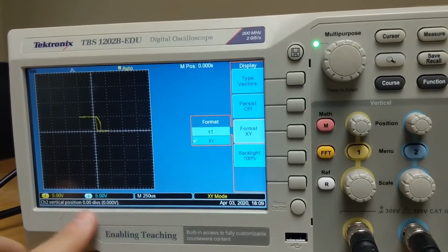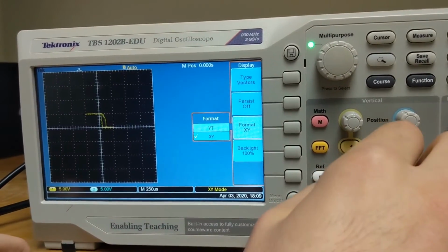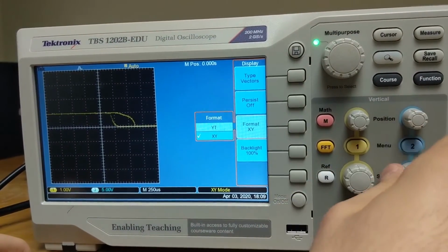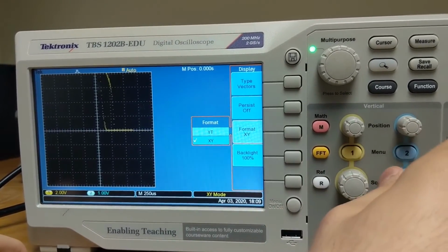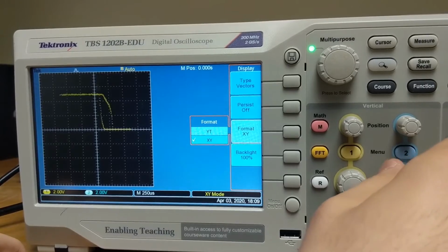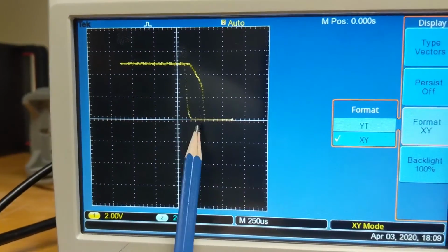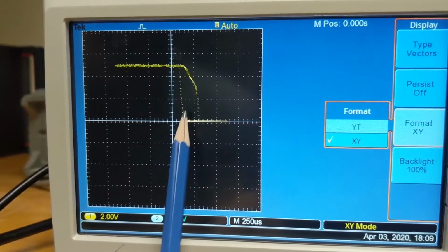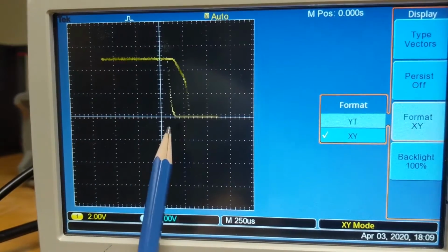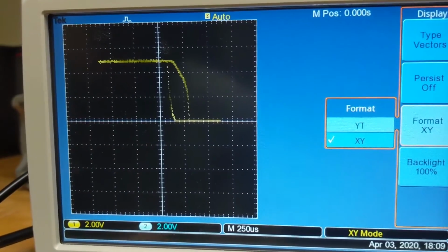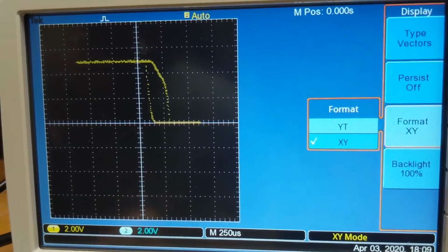Now that the two characteristics are of 0 volts, we'll adjust the scale to be able to read the 4 voltages. So maybe we'll make the scale of 1 volt and 1 volt, or maybe 2 volts. Okay. Now we can see this is what is called the hysteresis, that the curve is not continuous. When it's going one way, the other way is not the same one. So this doesn't affect our result. We're really interested in four voltages.